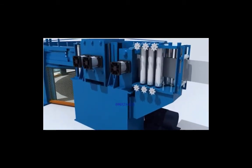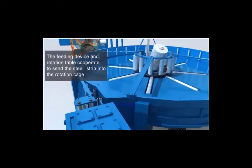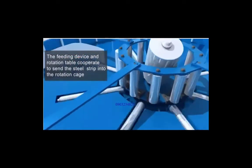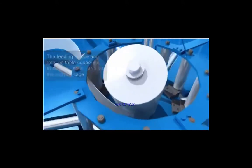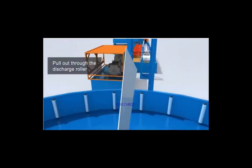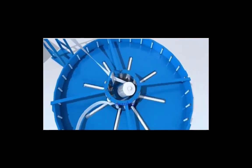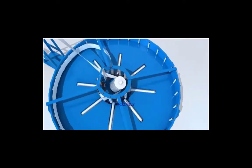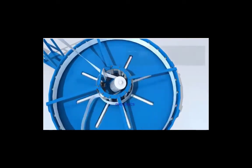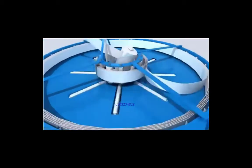The horizontal accumulator carries the steel strip through the feeding device and stores a certain amount of steel strip in the rotation table. The feeding device and rotation table cooperate to send the steel strip into the rotation cage and stop feeding when it reaches a certain number of circles. In this process, the steel strip changes from horizontality to verticality by the mobile rack. Then the main motor provides power to pull out the steel strip via the outputting device. The steel strip returns to horizontality.